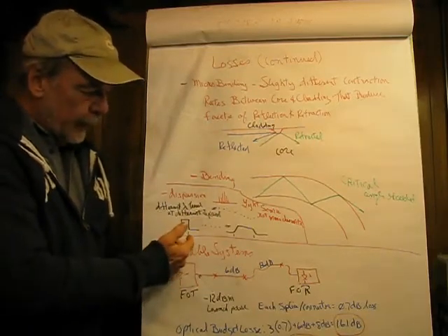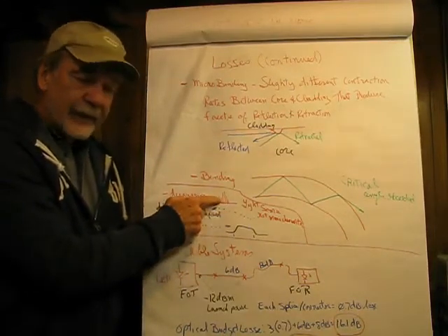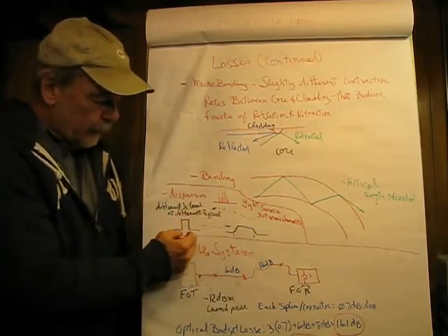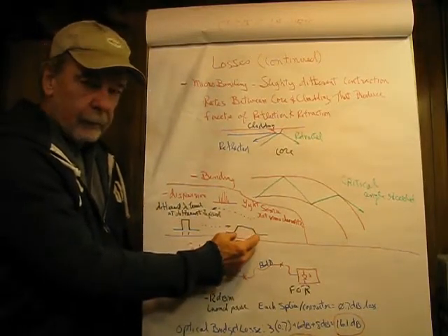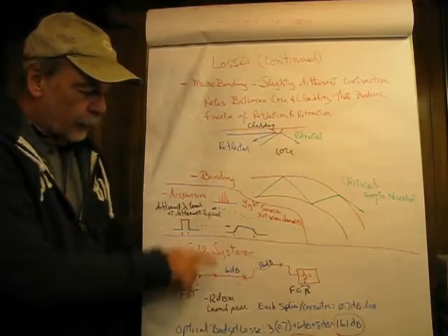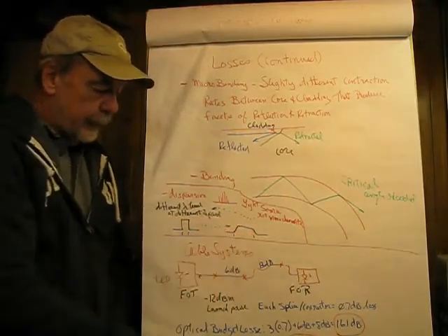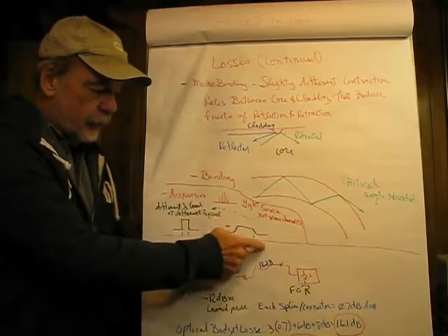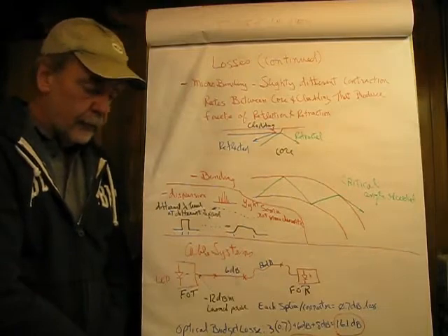So what we get out is not only attenuation, but different delays. What comes out of this is that the input pulse is spread out. And that makes it harder to detect when you have a signal, and further, the spreading can cause this energy to interfere with the energy of the next pulse, intersymbol interference.